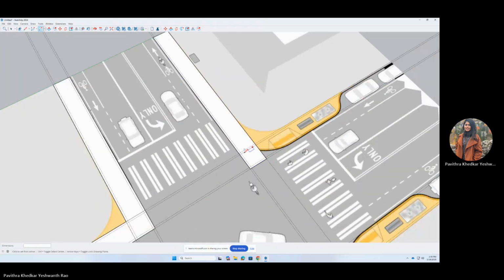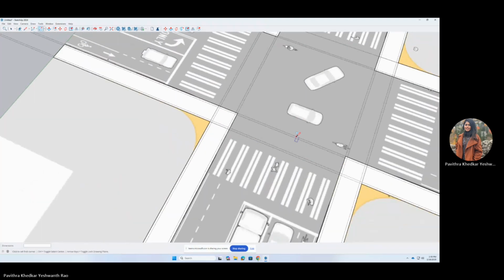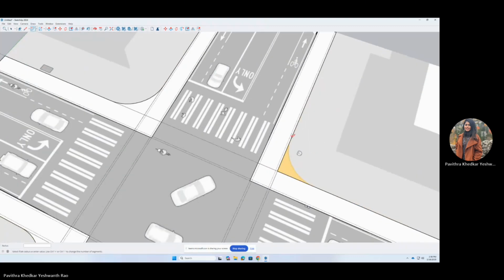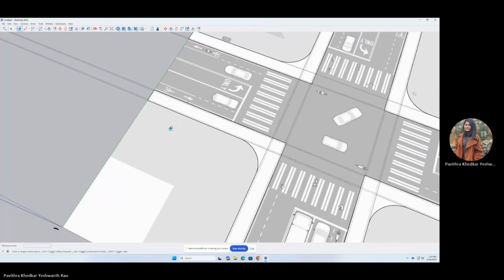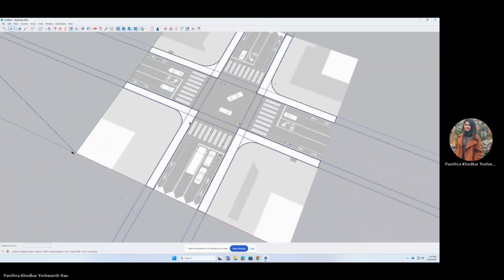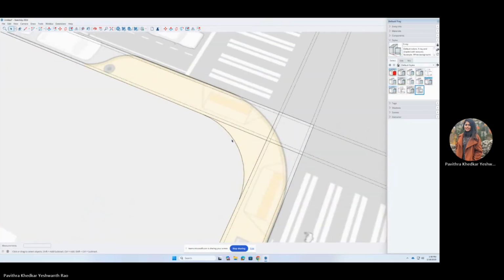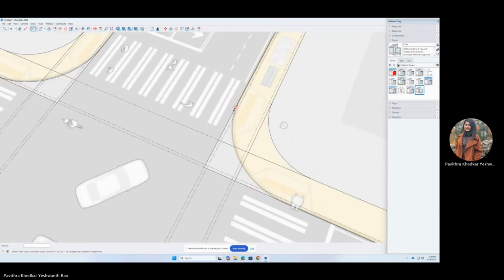JPEG images are pixel-based and may not be perfectly clear, so rely on precise measurements rather than visual estimations. Manually enter your dimensions on the keyboard. Use multiple guidelines to create a structured framework for the actual tracing. Keep the guidelines uniform and proportional to maintain design consistency. If necessary, adjust or reposition guidelines before tracing begins. Regularly zoom in and zoom out to verify alignment and avoid minor scaling errors.